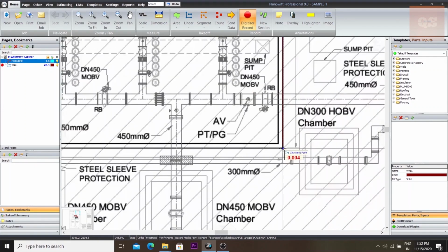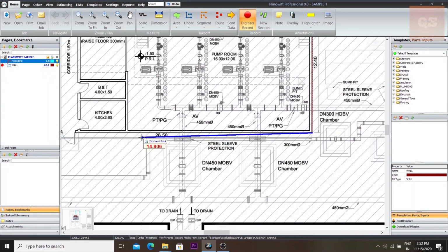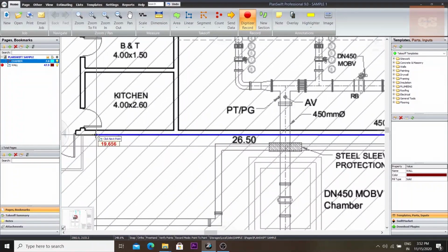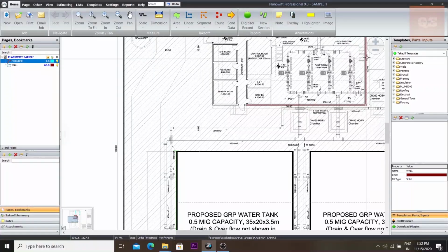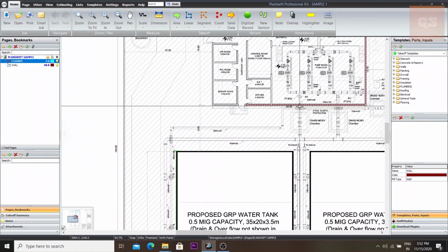Again you're clicking here, again you need to click the bottom also. So you need to measure till here. So finally you have done it. Click digitize a record. Here your wall measurement gets updated to 48. Previously it was 16. After calculating this part and this bottom part, it is coming to 48.8 meters.